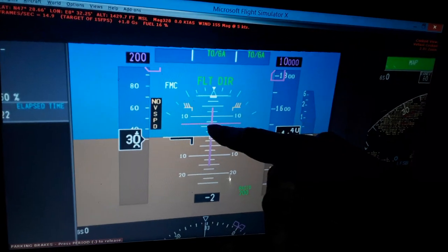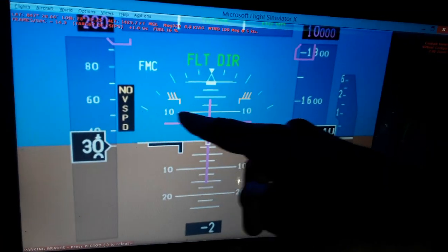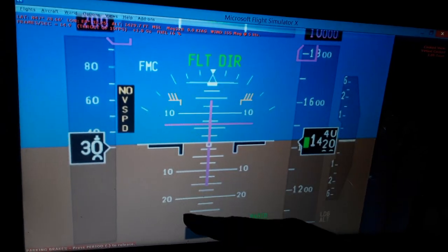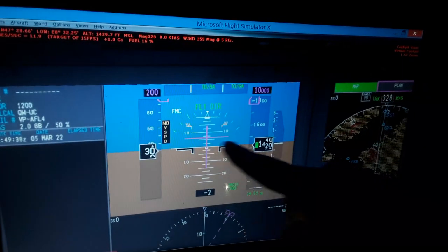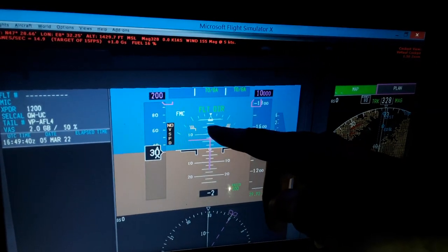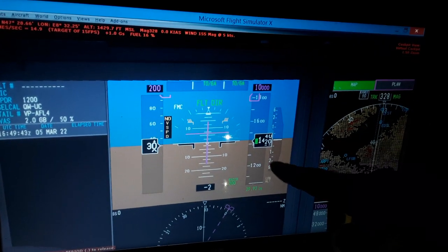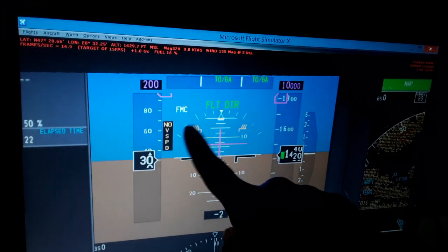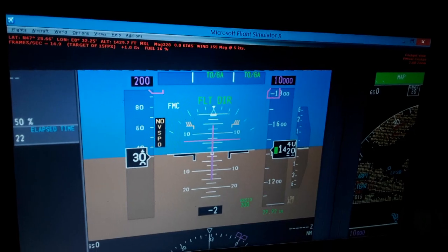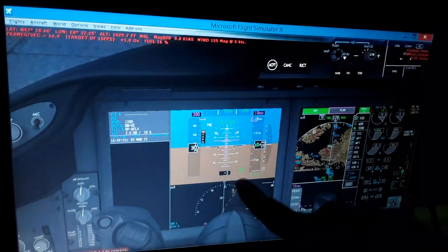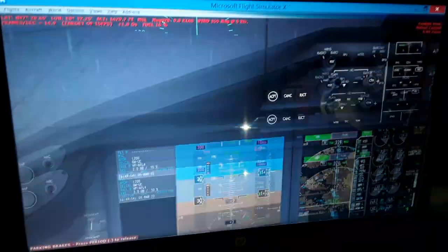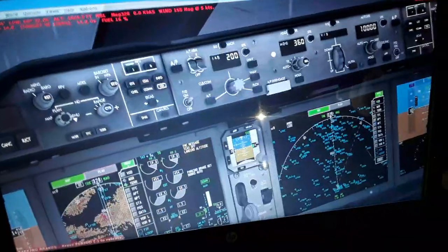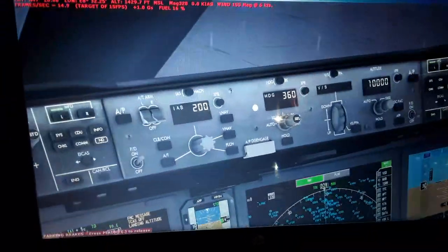It is 2.5, 5, 7.5, 10 degrees, 12.5, 15, 17.5, 20 degrees for pitch up and pitch down attitude. So you need to pay attention to both. If you have a positive attitude but the aircraft might be falling down, so you have to pay attention to this needle also. This is the bank angle in flight, how steep bank angles you make. Also this is the heading 360 degrees, so the purple values are the ones selected from the autopilot flight director system panel over here.